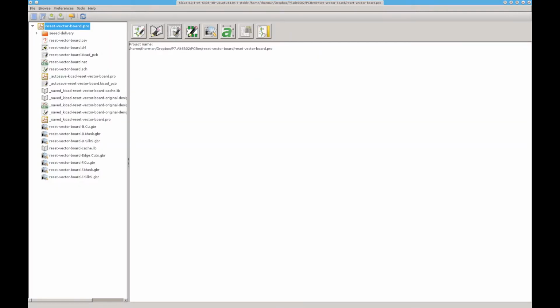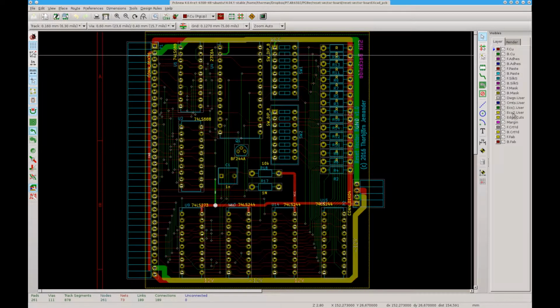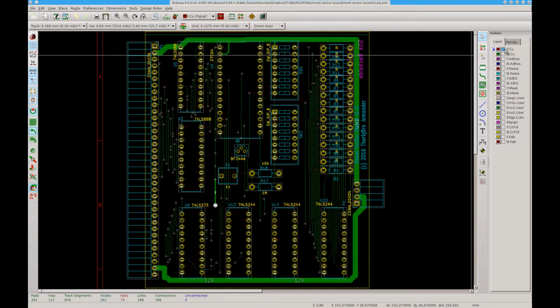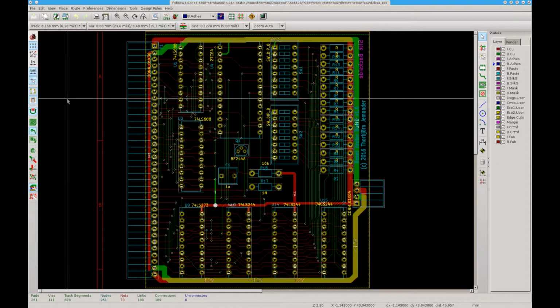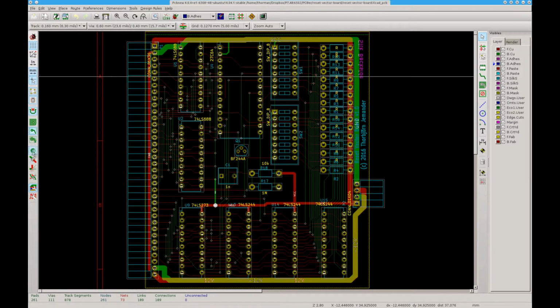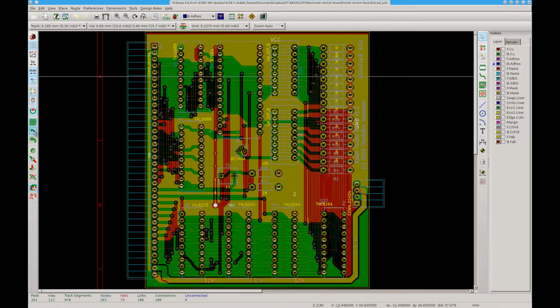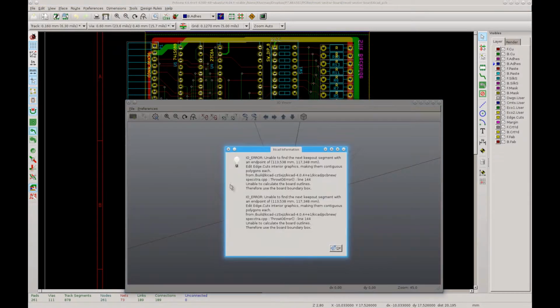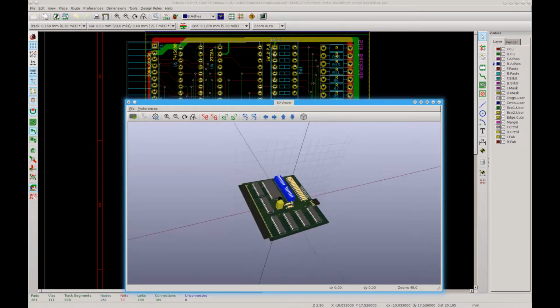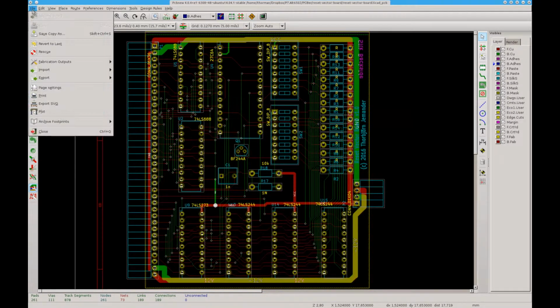In the layout editor, we have on the far right side all the layers of the board. You may choose which ones to visualize at any time and which one you want to edit. Next to that is a column with options for modifying the layout, like adding tracks, doing copper fill, or drawing text or geometric shapes on the board. To the far left we have the options for viewing the PCB, like whether or not to show the copper fill. There are lots of options and settings in this program, but I will use two functions later on. One is showing a 3D version of the board, and the other is to export stuff to manufacturing.